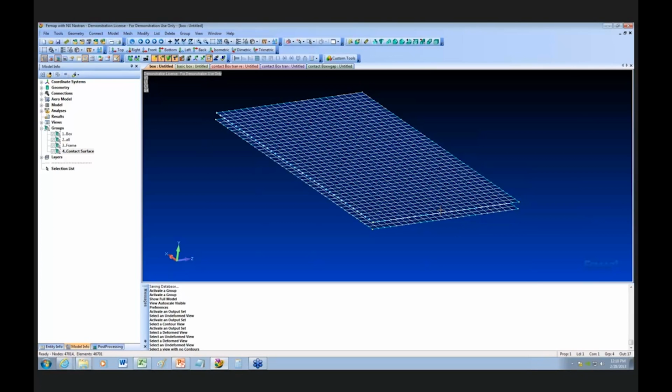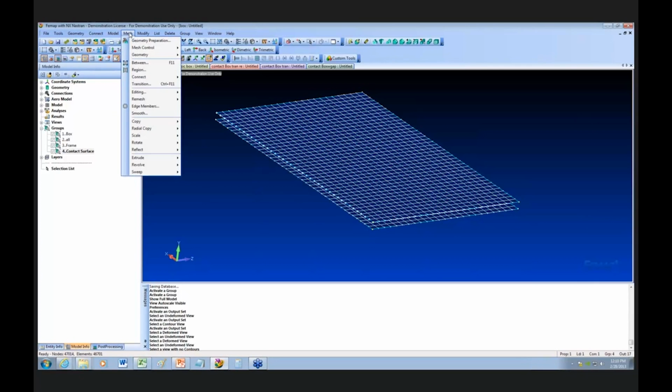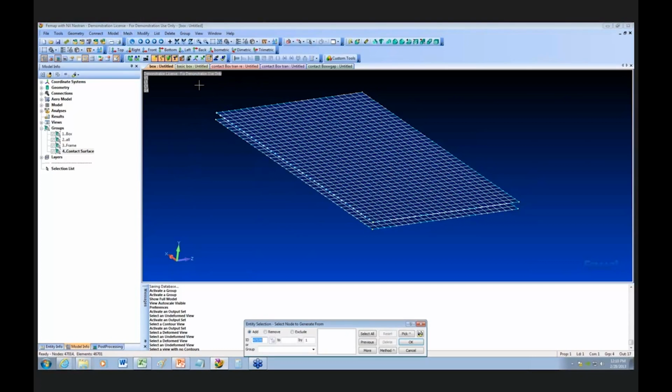And then in another case, I'm going to put gap elements. So FEMAP and the meshing has this little nifty thing right here. Let's see, connect right here, closest link. And this works great when both are set up and are symmetrical. I have the same number of nodes on both surfaces. They have the same dimensions, so it's going to work perfect.